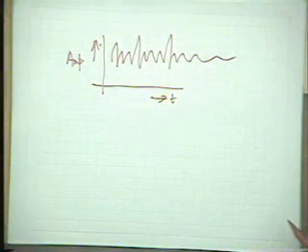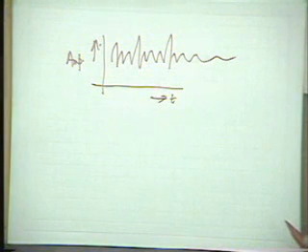This is quite rich in high frequency components, and let us say that we would like to take samples of this signal. Naturally, we can take samples at a rate higher than twice the maximum bandwidth of the signal. But then we have to keep a very high sampling rate, because this kind of signal is quite rich in high frequency components.